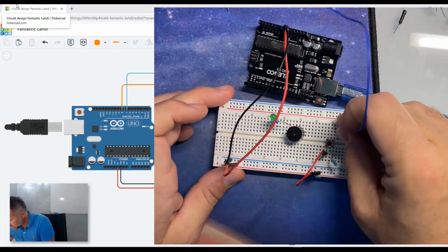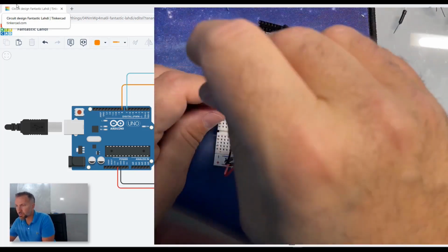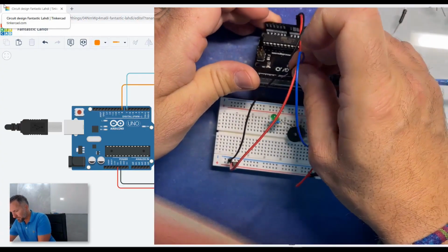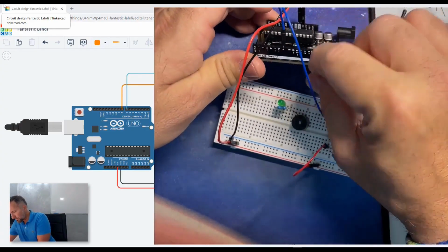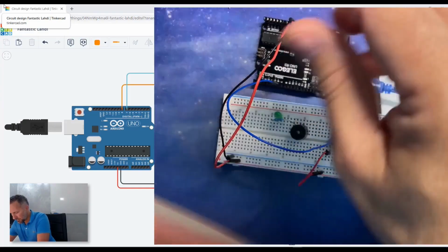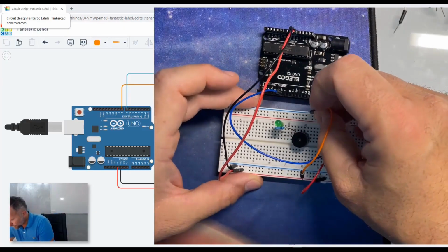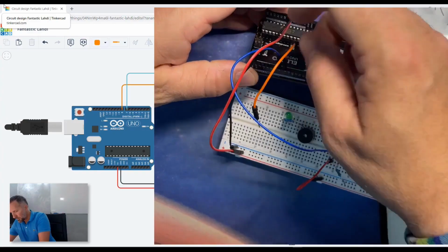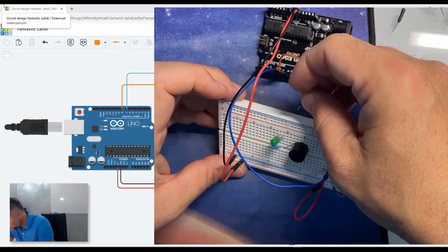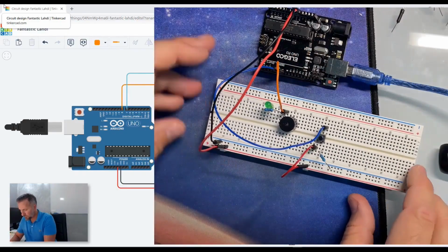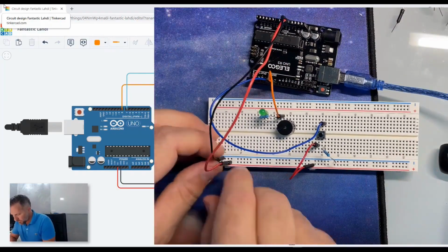The other part of the button, which is the one that will activate, we said the button is pin number 7. We chose pin number 7. The output that powers both the anode of the LED, as well as the buzzer, is pin 8. And we placed it here. Let's verify for a moment.